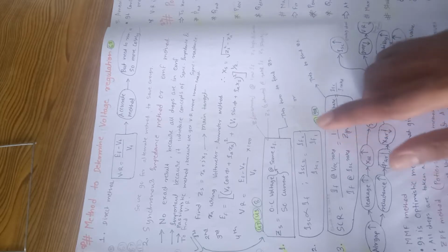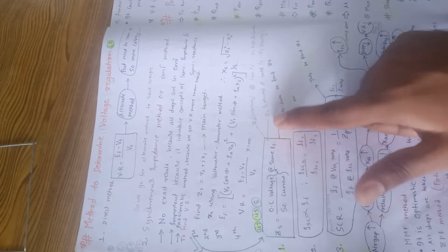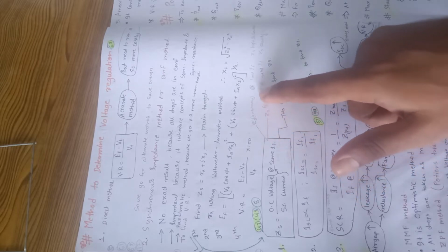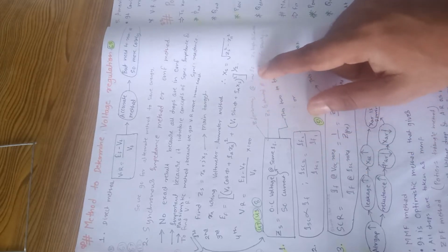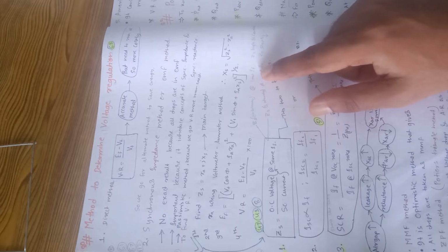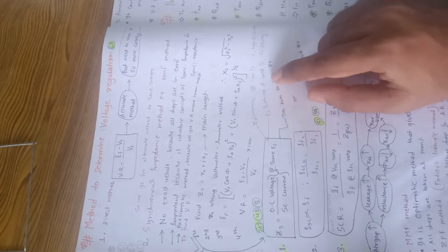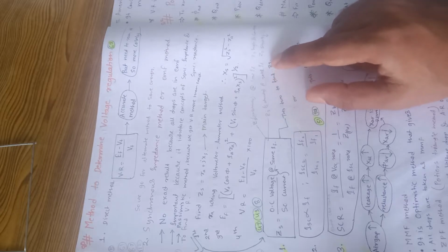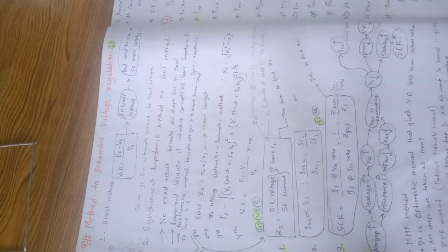Also we need to know that there are two types of ZS: one is unsaturated ZS and the other is saturated ZS. Unsaturated ZS is for low field current, that is higher, high and constant. Saturated is at the rated field current and is a comparatively lower value of ZS.